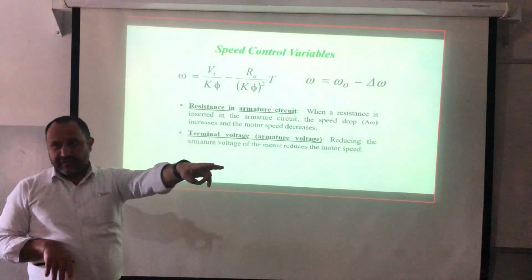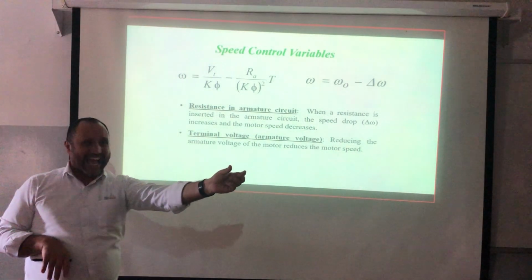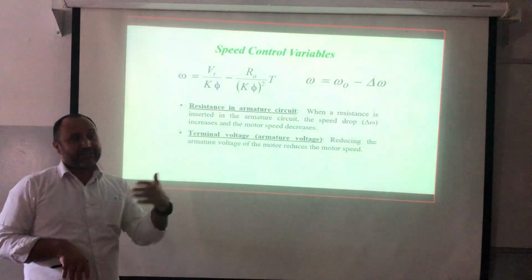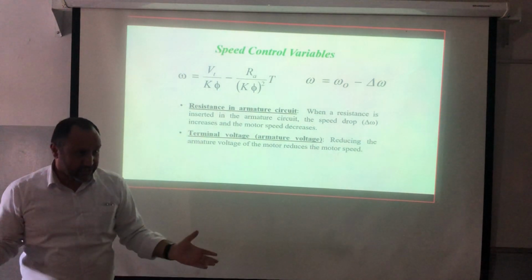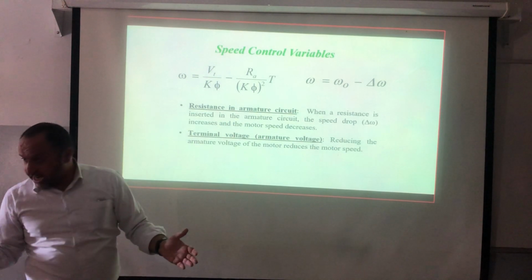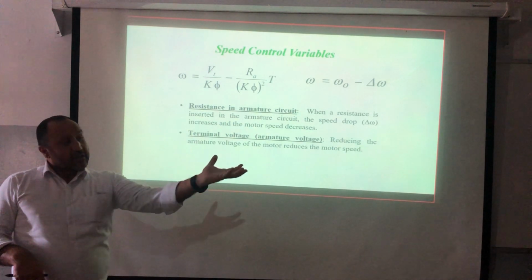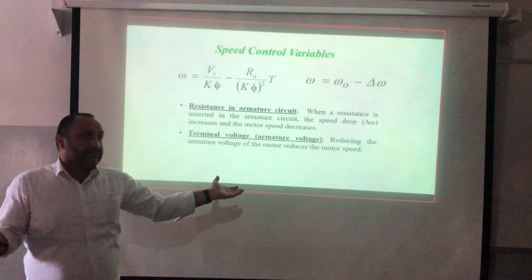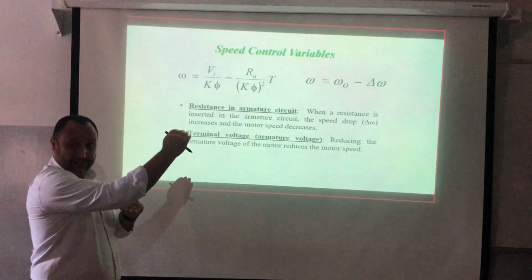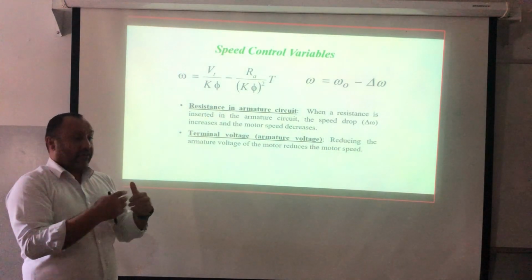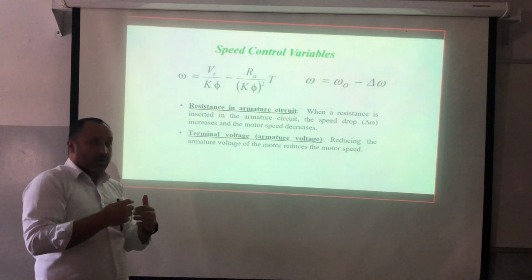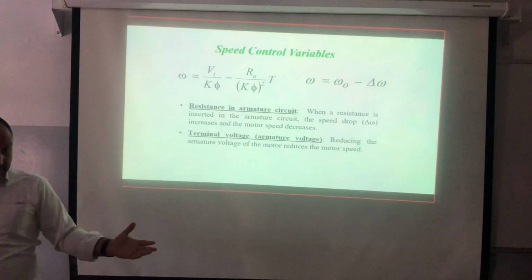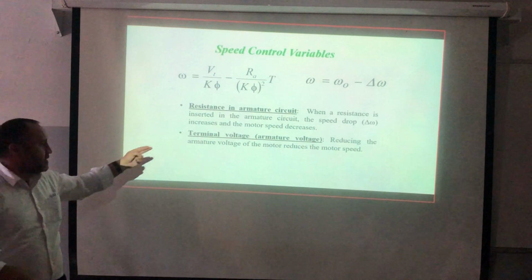The first reason is the insulation. The insulation can handle a certain voltage. The second thing, if I increase the flux, the core will enter saturation. Do you know the saturation? The flux curve. You are consuming more current than you need, simply because it is saturated. If I'm consuming more current than I need, the remaining current will go to losses.